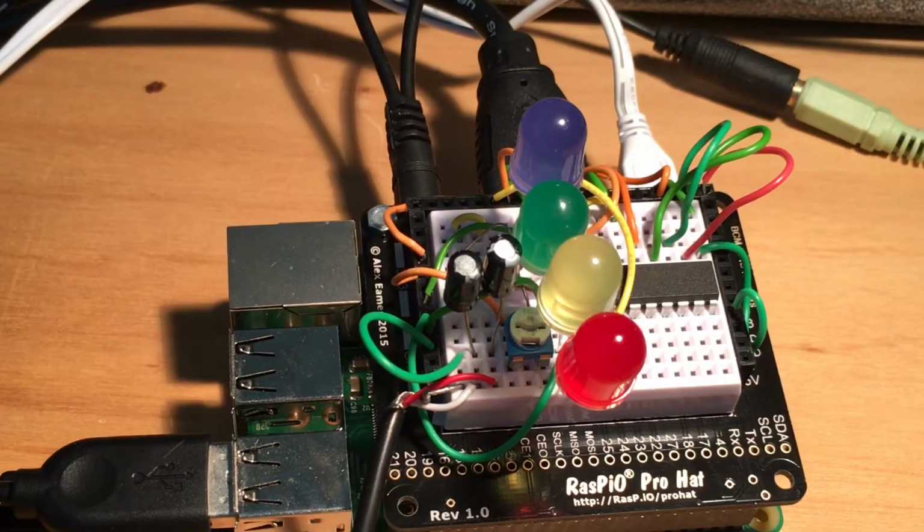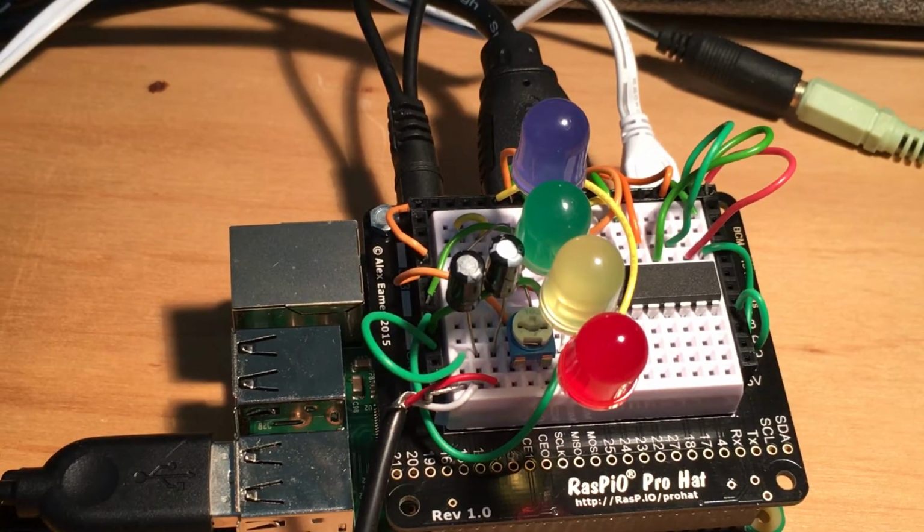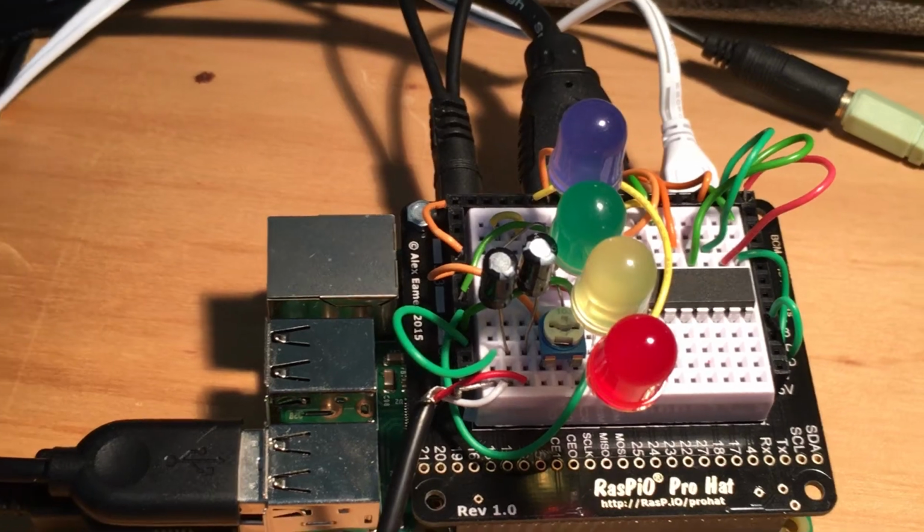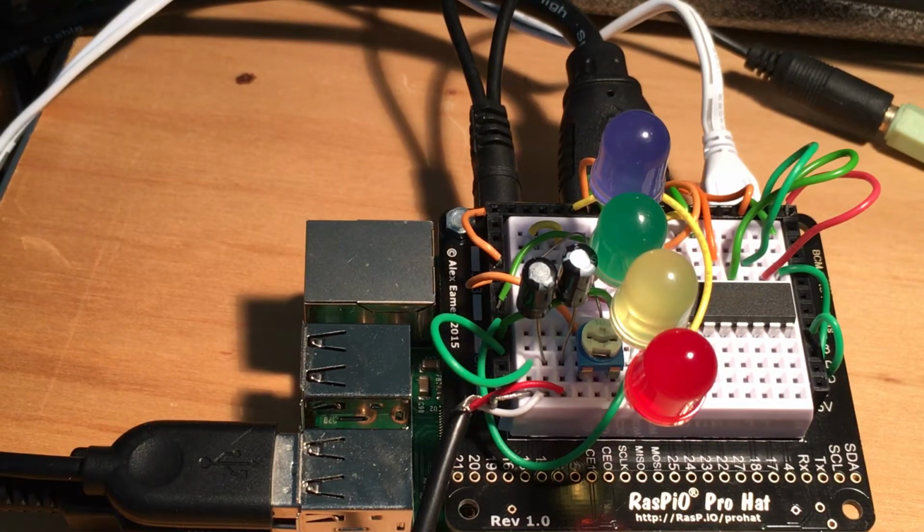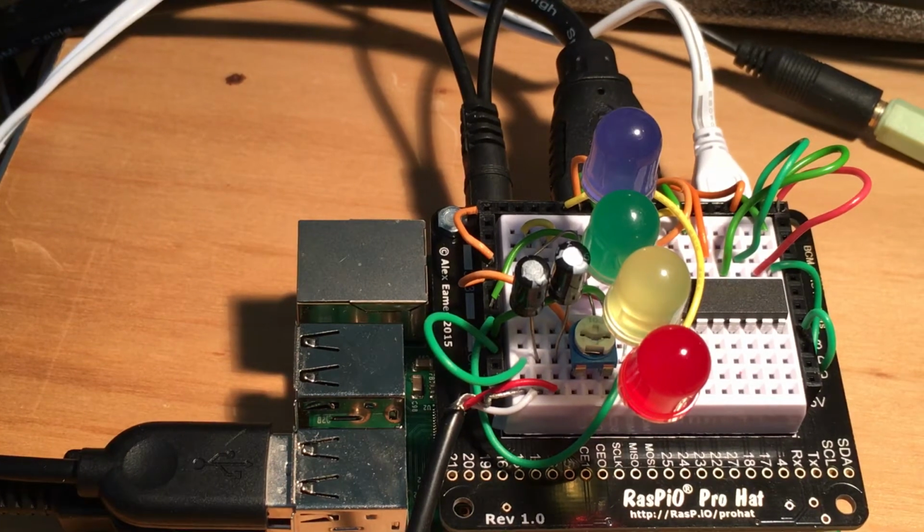So we see there quite a nice little project using 4 LEDs, quite a lot of the bits from the experimenter kit, the only 2 additions, I say, being the 2 10 microfarad capacitors, and their value is not too critical. I have tried down as low as 0.1 and slightly higher values as well, but that's probably a reasonable sort of median value to use.